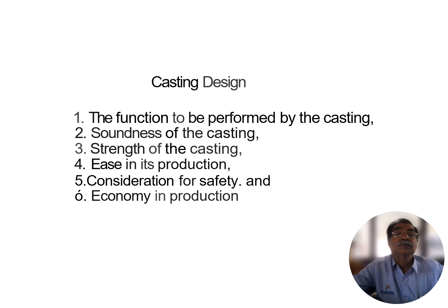The following factors must be considered in casting design: the function to be performed by the casting, soundness of the casting, strength of the casting, ease in its production, consideration for safety, economy in production. So, in order to meet these requirements, a design engineer should have a thorough knowledge of production methods, including pattern making, molding, core making, melting, and pouring.